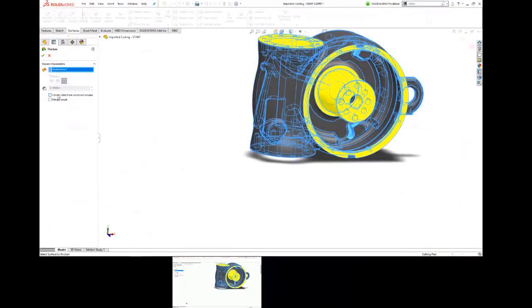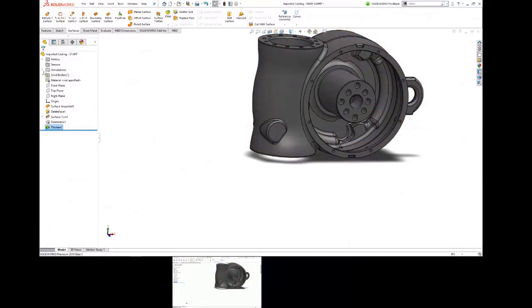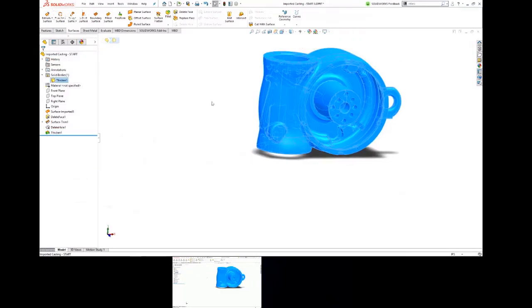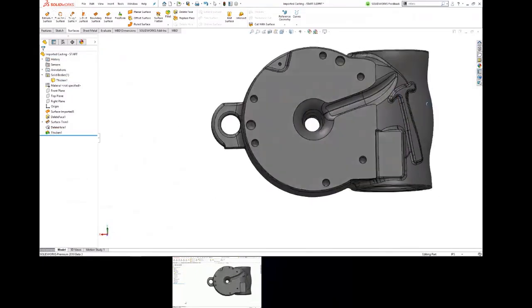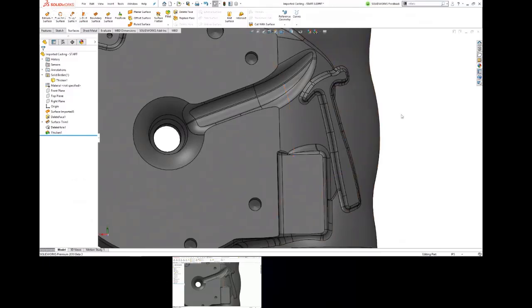If that's grayed out, that's another tip: not watertight yet. Still have some work to do. Well, let's do it. See what we get. All right, there we go. Now we have one solid body from that thicken command. And surprise, there's this weird little hammer-shaped extrusion. But you thickened it, so there's still possibly a cavity inside?